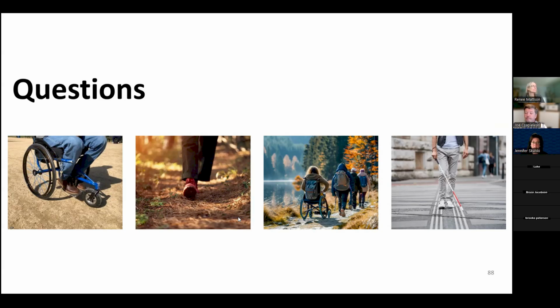They replenished it, but it continued to be susceptible to rain. It was also part of the area where maintenance staff were driving their truck, which was putting additional ruts through the crushed limestone. Finally they said, on this segment we're going to pull it out and put concrete, and the whole rest of it will continue to be maintained as crushed limestone. So it doesn't mean that you have to commit to one singular surface.